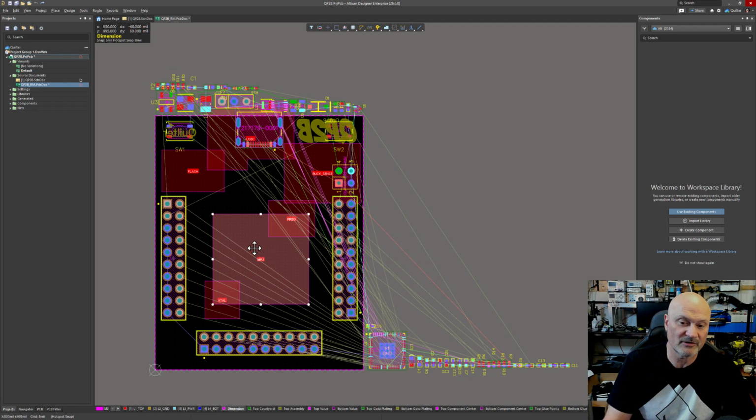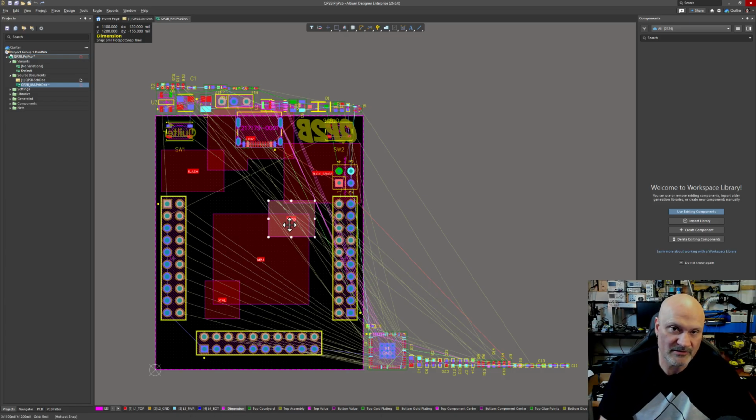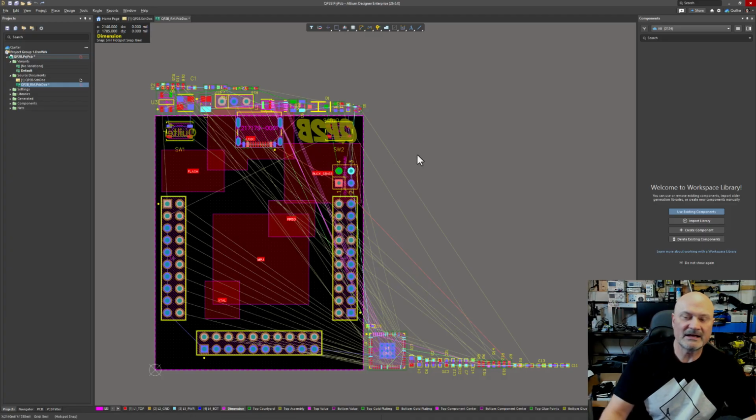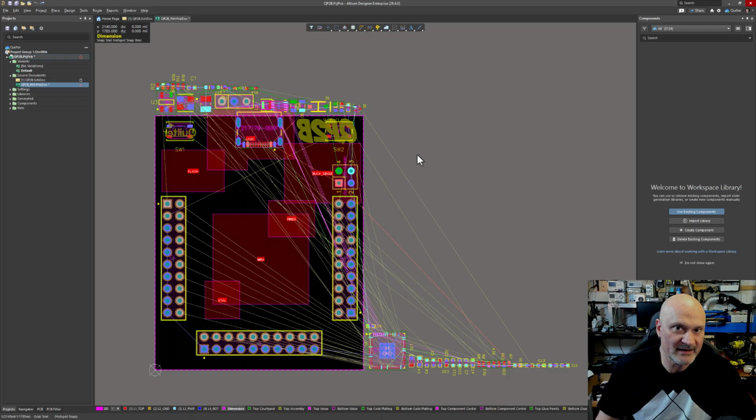So what's going to happen here is Quilter will move the microcontroller into this MPU room. It's going to make sure that the inductor and bulk storage caps for the RP2350 DC to DC converter should go in here. And even without rooms, I could get a decent placement because Quilter is smart enough to know what a DC to DC converter is and all of that. So we'll look at that in the next step. But what we want to do now that our design is prepared is we're going to submit that to Quilter.